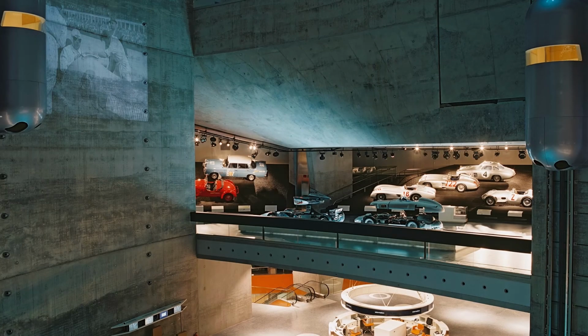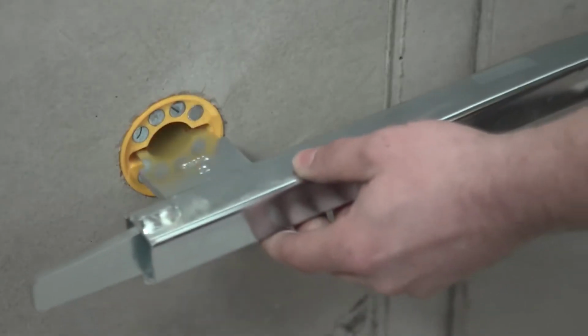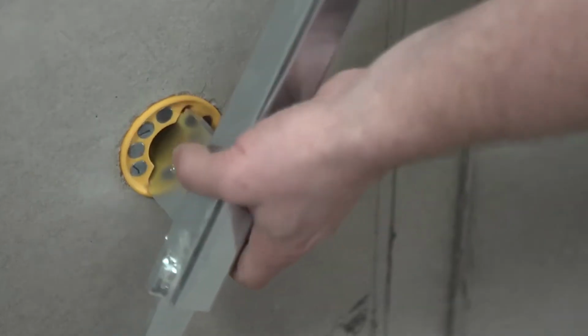This results in the following exposed concrete surfaces. If you take a closer look, you can see the following holes. This hole is caused by removing the inserted cone during the bolt installation. If this hole is left intact, it may increase the risk of corrosion on the rebar and cause fracture. To prevent this, a filling process is carried out.